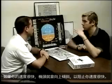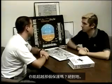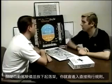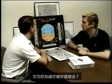If you get fast, the nose will pitch up to keep you from getting fast. Can you override that protection? Absolutely. You go gear down on the 320, you're in alternate law, what will occur? Gear down with the autopilot off, and you're going to get into direct law. Okay. How would you know that you're in direct law?